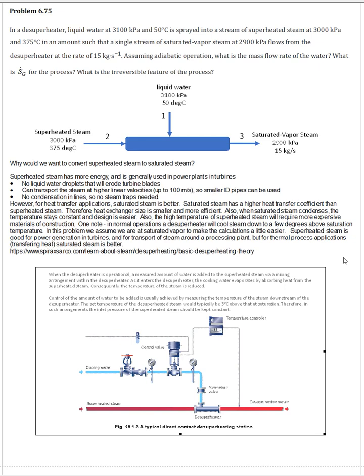And so you could think of this as probably due to, for example, the density. Saturated steam is going to be denser, and it will be able to transfer its heat energy, its thermal energy, to the pipe wall, and then across the pipe wall, and then to the other fluid that you're trying to heat up much more efficiently. So you can use smaller heat exchangers, more efficient heat exchangers.